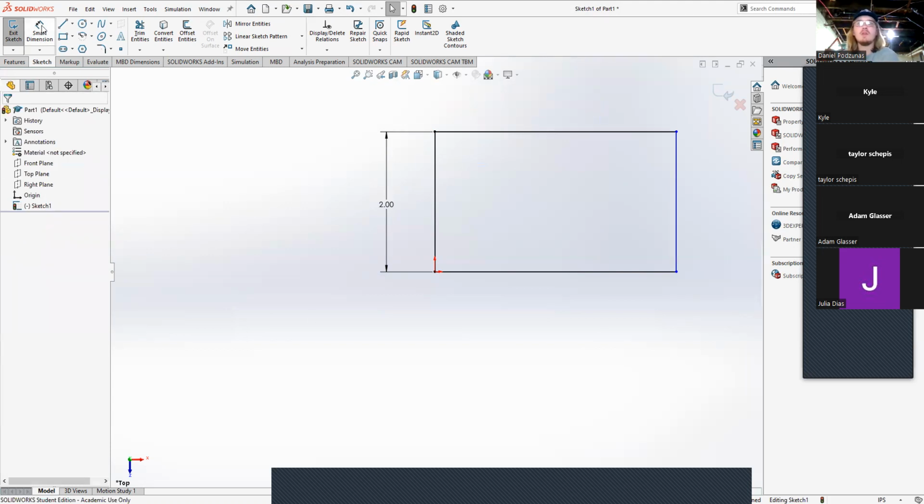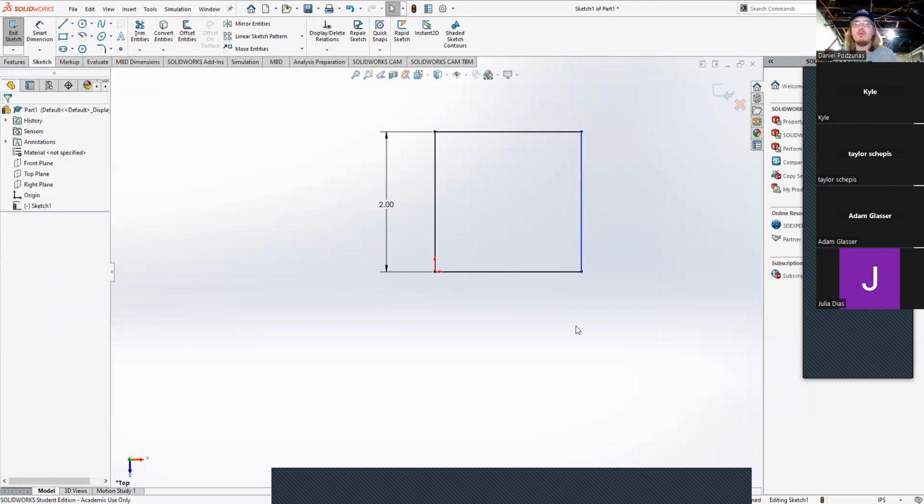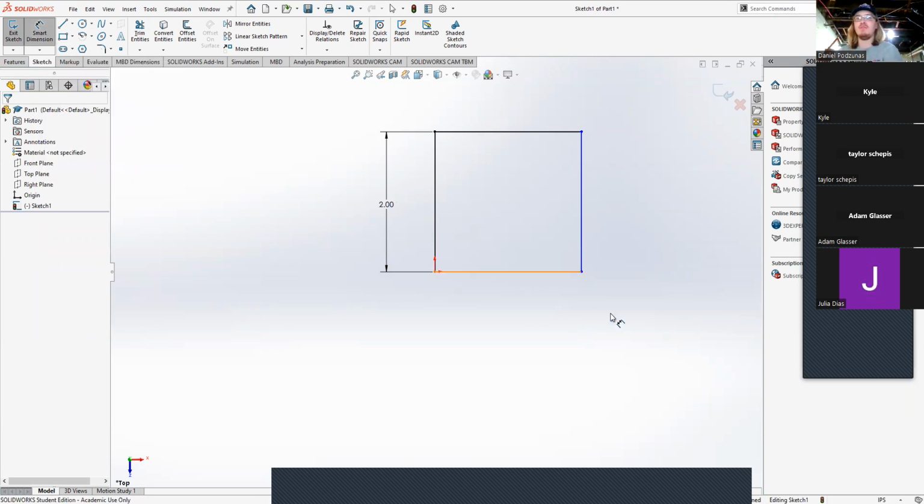That makes sense. Cool. So it's almost like you're adding enough rules where the sketch is definitely doing what you want it to do. And it is best practice when you're doing a sketch, even if everything's where you want it to be, to add dimensions, and later on we'll cover relations. But for now, make sure all your lines are black. You don't want to have any blue ones because that means there might be something you're not accounting for. So in general, it's best practice to try to have everything be fully defined.